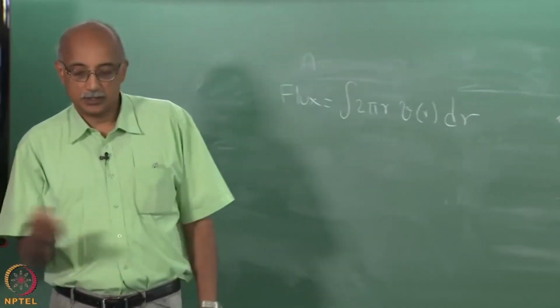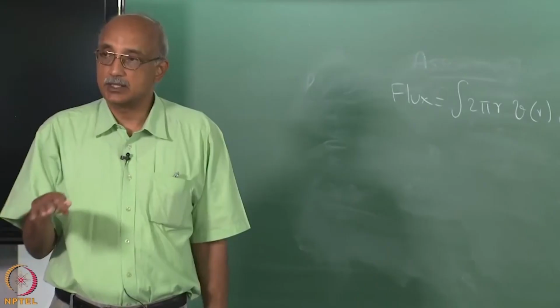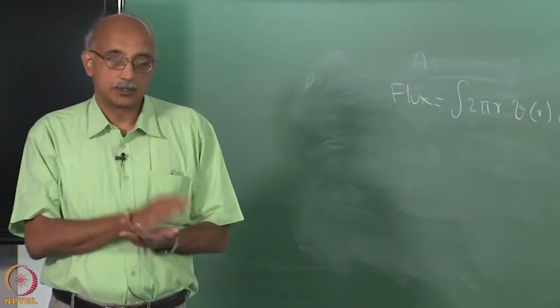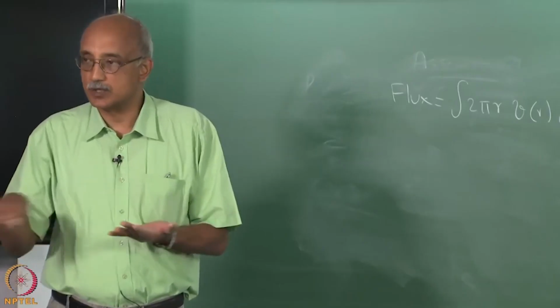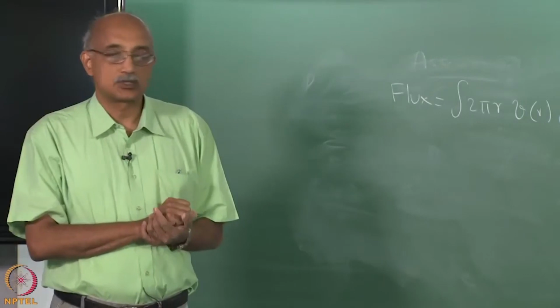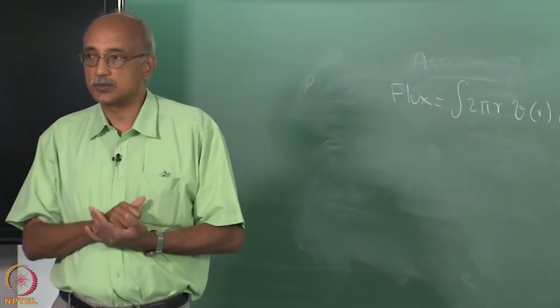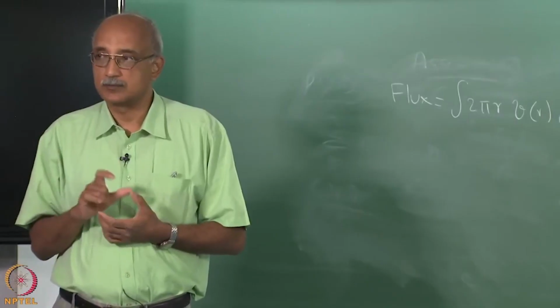As we mentioned earlier, it is the diffusion through the boundary layer that ultimately transports the reacting species as well as the species that should be adsorbed on the surface to the substrate. So, the final resistance to that is the diffusion through the boundary layer. So, the boundary layer thickness becomes an important parameter.